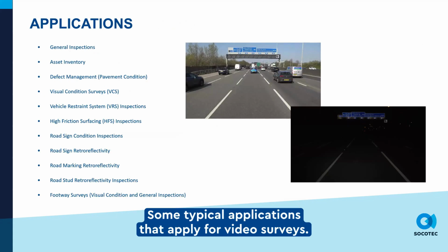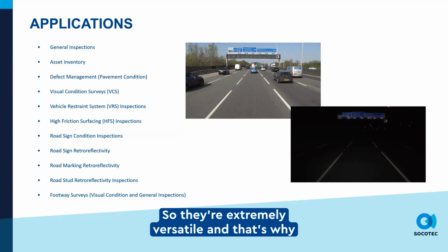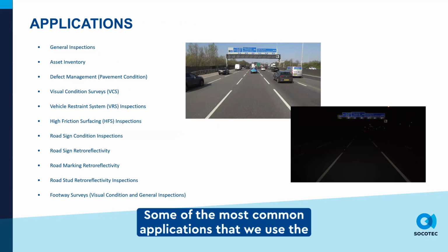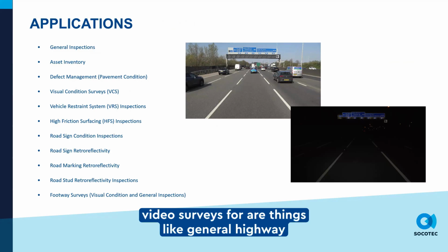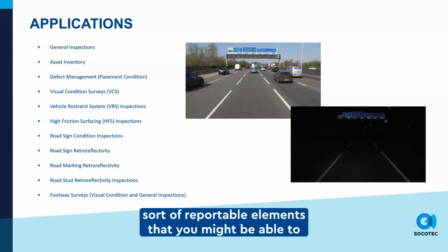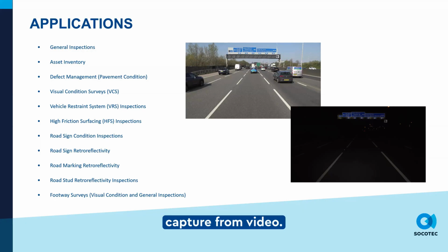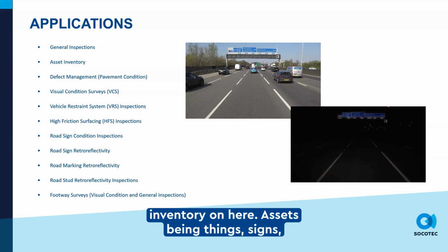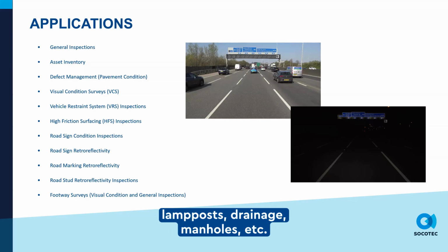Some typical applications that apply for video surveys. They're extremely versatile, and that's why they're now used across a wide range of highway applications. Some of the most common applications are general highway inspections. This can be looking at excess vegetation and any other sort of reportable elements that you might be able to capture from video. Asset inventory. We can create and update your asset inventory on here. Assets being things like signs, lampposts, drainage, manholes, etc.